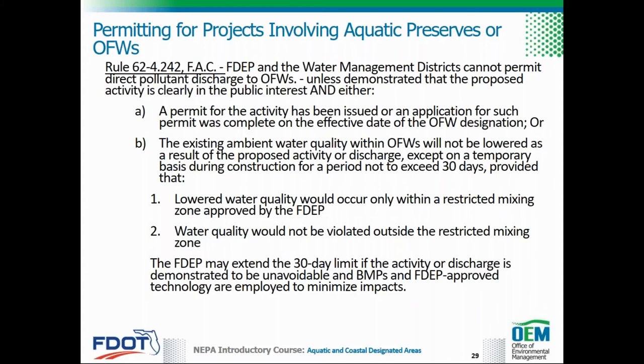Pursuant to Rule 62-4.242 Florida Administrative Code, no permit or water quality certification will be issued for an activity that will discharge into an OFW unless it is demonstrated that the proposed activity is clearly in the public interest and either a permit for the activity has been issued or an application for such permit was complete on the effective date of the OFW designation, or the existing ambient water quality within OFWs will not be lowered as a result of the proposed